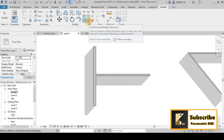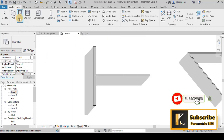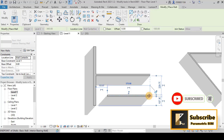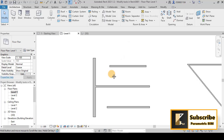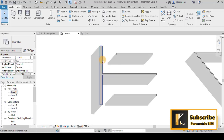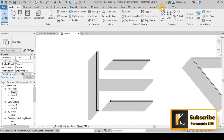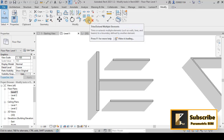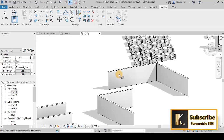And for the application of trim extend multiple elements, sometimes you can have multiple interior walls and you changed the position of this, and there will be a gap between them. You can simply go now to modify and choose trim extend multiple elements, choose the element that you want to extend to, and then 1, 2, it will be extended automatically like that.